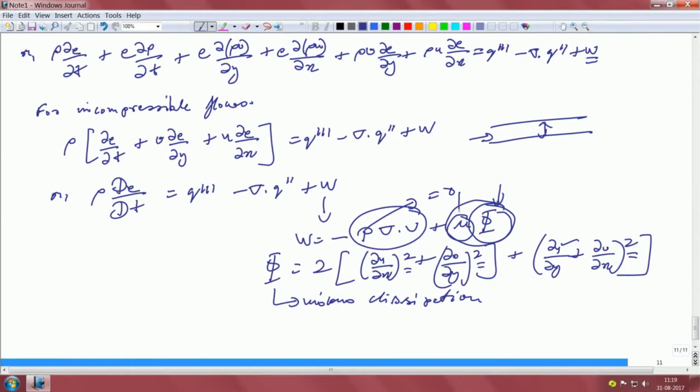If your viscosity is high, it can also have effectively the same effect. That means, if you try to push a very viscous fluid through a very narrow opening, you can generate a lot of heat. This is sometimes what happens in lubrication, in bearings and other things. Things can get hot also. So, that is the expression for that.